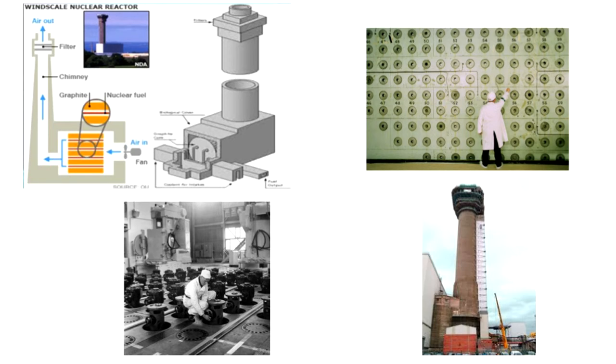However, instead of a gradual release of energy, the high temperature caused the built-up energy to be stored in the core. In hopes of accelerating the Wigner process, the operators increased the power even more. Due to the poor placement of Reactor 1's thermometer, the operator could not get a read at the core's highest temperature, causing the operators to be unaware of the dangerously high temperature. This led the temperature to exceed a maximum of 400 Celsius. On the morning of October 10th, operators noticed the extreme condition and proceeded to venture to the charge face in protective gear to secure the inspection plug.